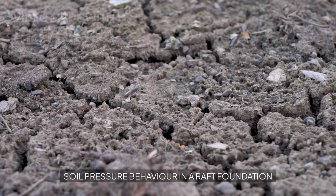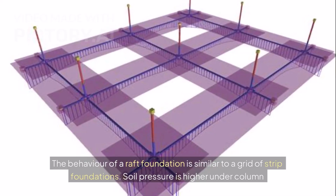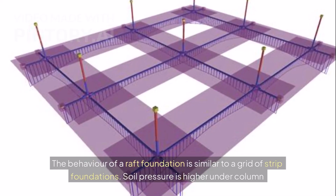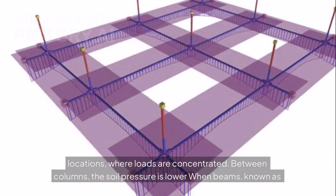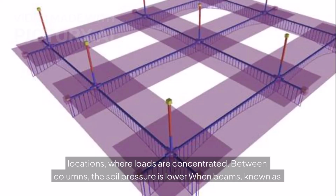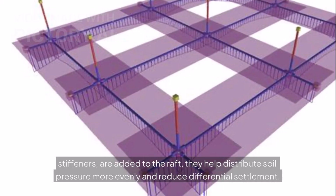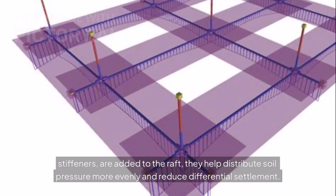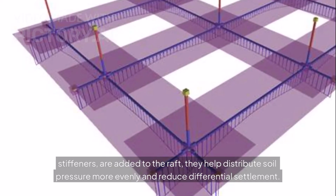Soil pressure behavior in a raft foundation. The behavior of a raft foundation is similar to a grid of strip foundations. Soil pressure is higher under column locations, where loads are concentrated. Between columns, the soil pressure is lower. When beams, known as stiffeners, are added to the raft, they help distribute soil pressure more evenly and reduce differential settlement.